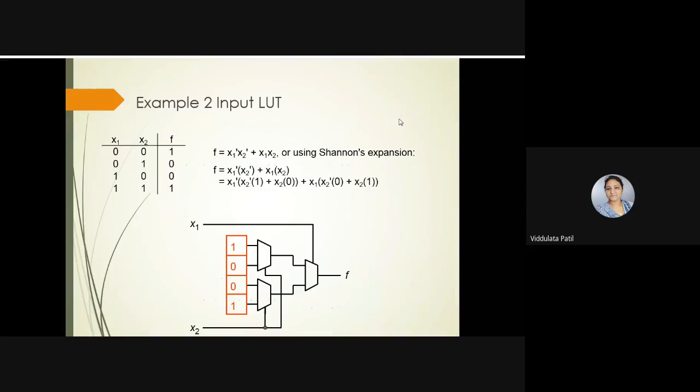We have discussed this part in the earlier session, that this is an XNOR implementation using a lookup table. Here the inputs that are given, that is 1001, are applied at the inputs of these multiplexers depending on whatever our function is.